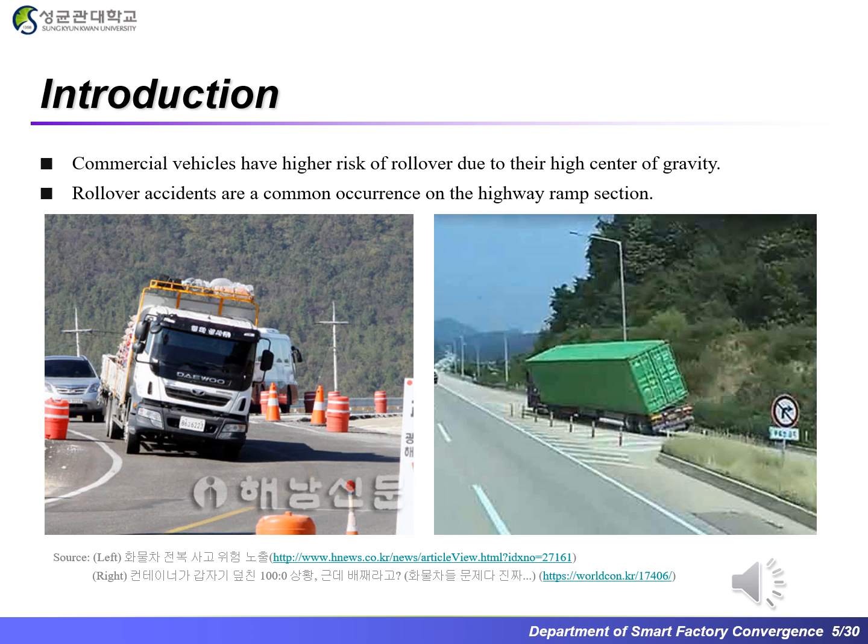Commercial vehicles such as buses and trucks have a higher center of gravity than passenger cars. When carrying passengers or loading cargo, the center of gravity is higher and is more affected by lateral force. As such, the risk of overturning is high, and in the event of an accident, it is easy to cause a major accident. Rollover accidents commonly occur on curved roads, such as highway ramps. It is particularly prone to accidents on steep bands or downhill.